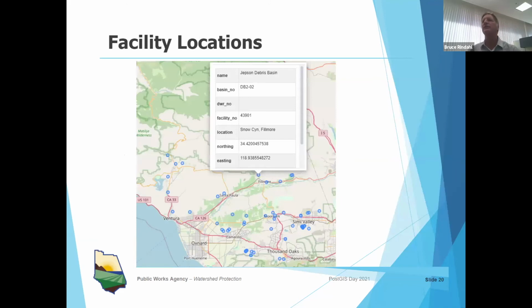First off, we have the facility location. There are all the various locations that we're concerned about. Two things you notice: the easting is wrong. It should be a negative number. So make sure you get the pluses or minuses. Most everybody in the US just gives a positive number. They assume you know what west is. And yes, we have locations down to the nanometer for the northing and easting, but that's the data you get.